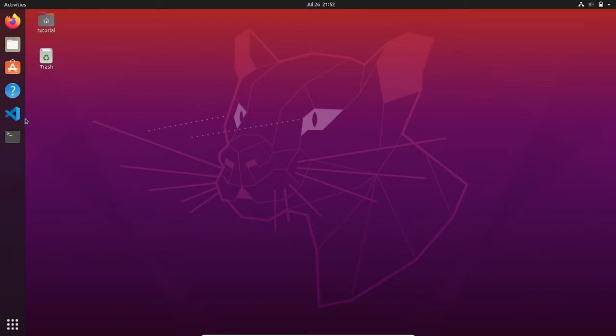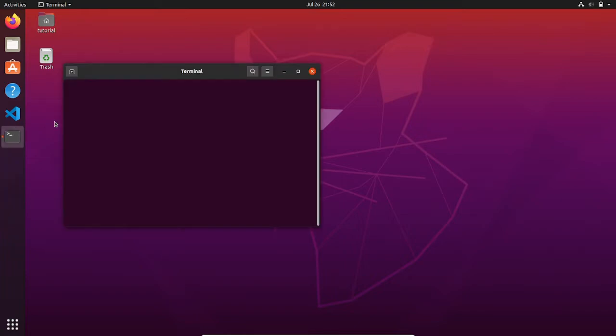planning problem. If you want to access that, you just need to open a new terminal and then type rviz launch and then the name of the package that we have set up in the configuration package using the setup assistant, and that is going to be cobots_moveit_config, and then we're going to launch the demo.launch.